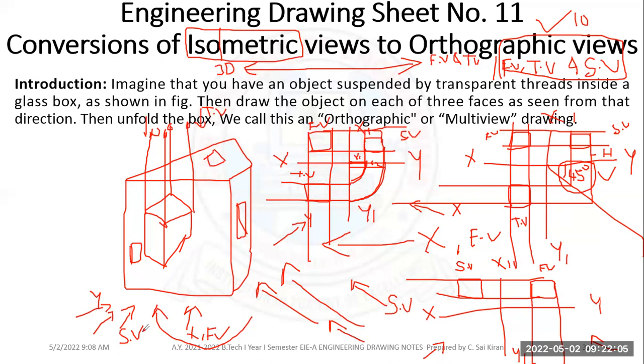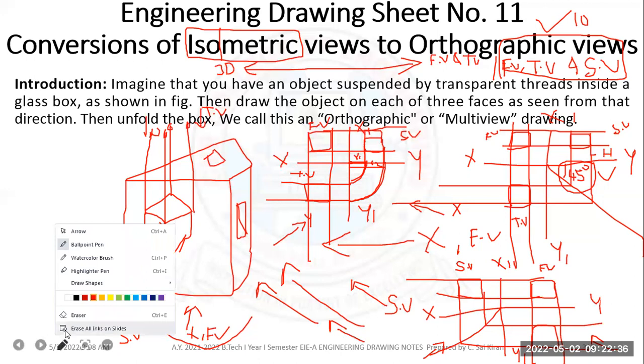And because this is my front view, I'm looking from this side. Front view will be on the right side of the x1 y1 line, and this is my side view. So the side view will be on the left side of the x1 y1 line. And below, you have to draw the top view: take a 45 degrees line from the center, project till here and project till here, and then from here draw the horizontal line. From here draw the horizontal line, and this is my top view. Okay. So this is a basic explanation.